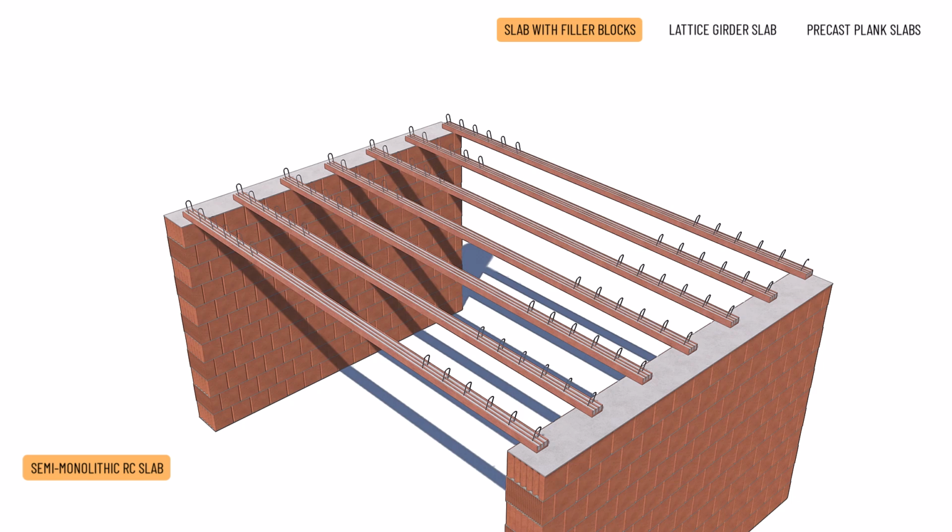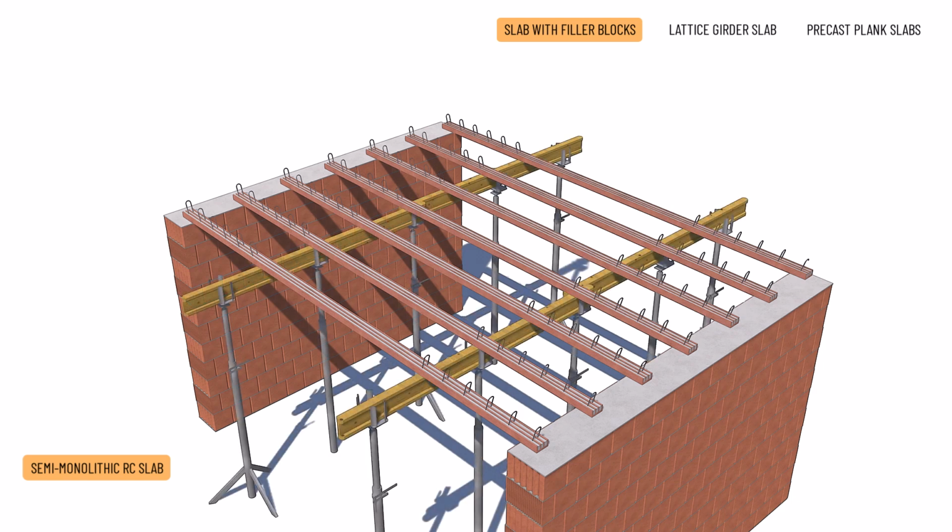The tops of the walls must be protected against moisture by insulating sheeting and laying the cement-based mortar under the joists. For the duration of the construction, the joists must be supported at intervals of 160 to 175 centimeters and should be removed after the monolithic slab has fully hardened after exactly 21 days.